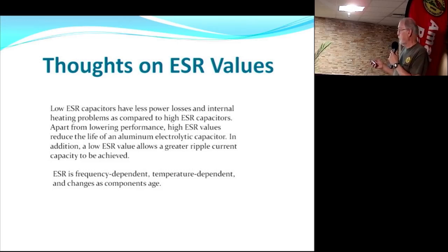ESR values are important. You want them to be as low as possible. You can read what's on the slide. They are temperature dependent. Your electrolytics are sitting in the car. It's 130 degrees. They're rated at 90 degrees, or they're in your equipment. The fan goes out on your switching power supply or your linear power supply. Those capacitors are not going to like that. They just are not going to be tolerant of excessive heat.